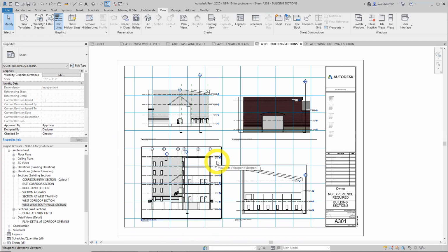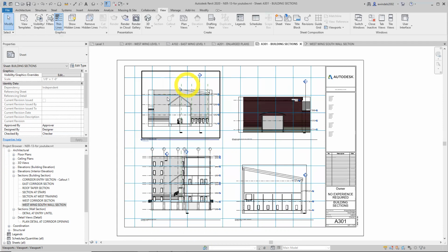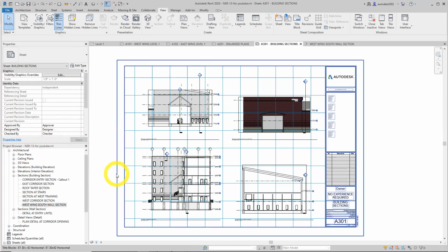We're going to modify some viewports next. So very similar to AutoCAD, viewports are dynamic, showing what we want, say between a model space in AutoCAD and our paper space. This is kind of like our paper space in Revit, and our model spaces are all over. We have several, and our whole model merges them all together, but it's a lot different in the way that any view, anything you change in the original view, like I just did here, is reflected in this view initially. So AutoCAD's not quite that integrated in its views between each other, between different spaces as Revit is.